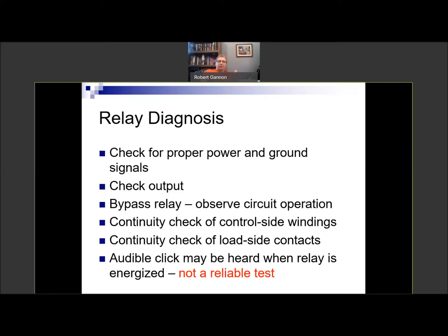To diagnose it, well, we did this in the online lab. We did a relay diagnosis. First thing we did was pull the relay out, and if you recall, we checked to make sure we had power and ground where we needed to have power and ground. Then we used some method to check the output. We bypassed it. So let's go back to all data